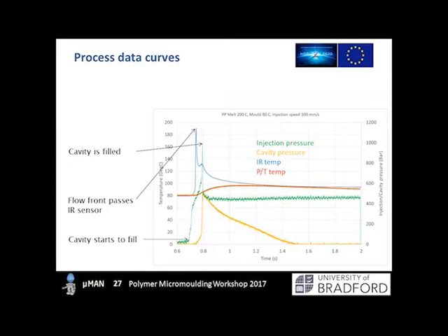So this is the filling profile here. Basically that's happening in just a few milliseconds. This is for a reasonably large component. But we can generate all this kind of data, and we can start to see when things are occurring. So we've got injection pressure, we've got infrared temperatures, all these things we can use to quantify what's happening in the cavity. And it's also very useful for benchmarking simulation software as well.